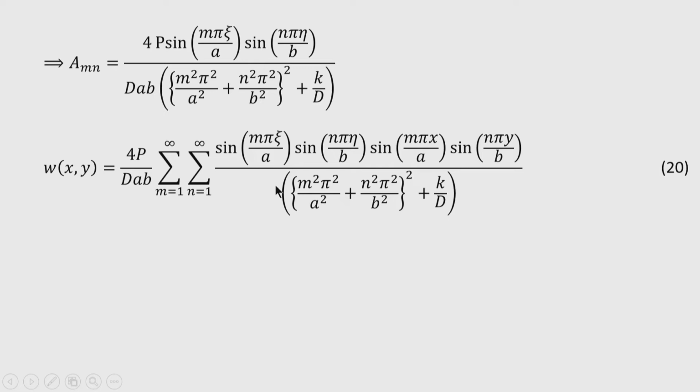Now, a problem can have more than one concentrated load, for example when a bridge deck is subjected to vehicle loading, because a vehicle has several axles. Each axle has two wheels, right and left, and therefore it will impose two concentrated loads per axle generally. So, you will get multiple axle loads, that is, multiple concentrated loads. In that case the deflection at any point can be found by the principle of superposition, because we are only dealing with linear analysis.